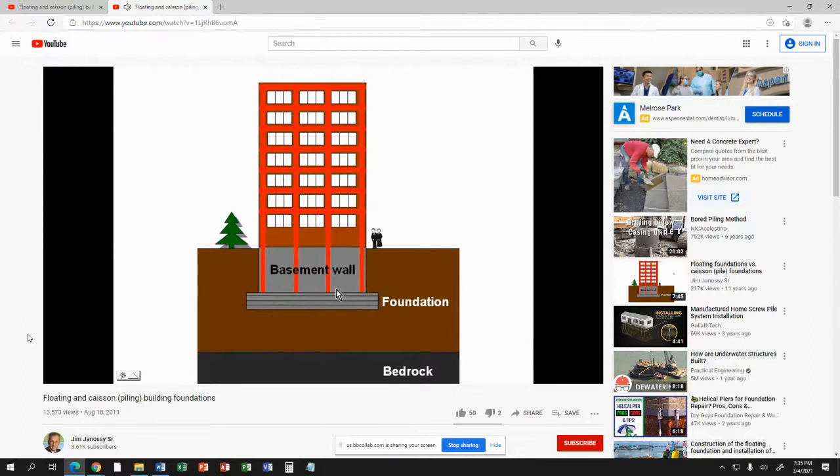And if the architect were lucky, then the moisture in the ground and the softness of the ground in various areas wouldn't vary too much down here in the dirt. And this building was expected to settle, but it might settle evenly if they were lucky. Now, there is a layer of bedrock underlying Chicago. It's 40 feet down or perhaps further, but there wasn't a very convenient way of reaching it with the technologies available for excavation in the 1880s. So many buildings were constructed this way.